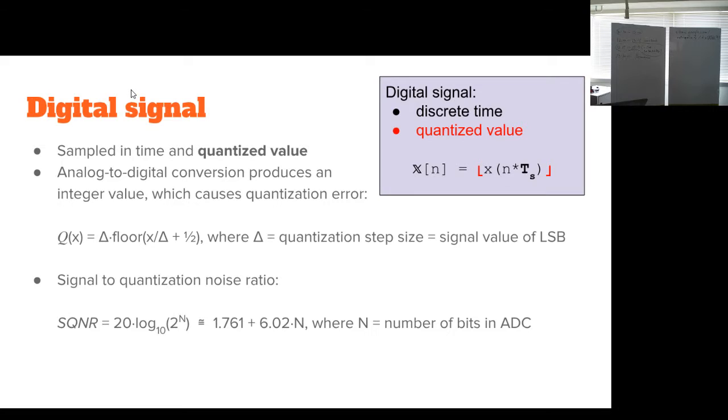Okay, 50 decibels. If you think of your hearing, that 50 decibels is actually enough for spoken voice, since spoken voice is quite monotonic. 8 bits is enough. But how about a symphony orchestra? What is that? The very low volume parts and very high volume parts. The dynamic range can be 100 decibels. You cannot store it with 8-bit resolution,